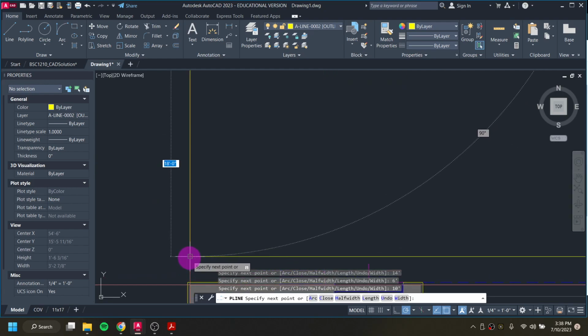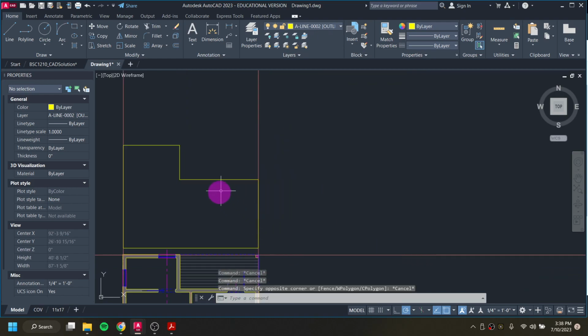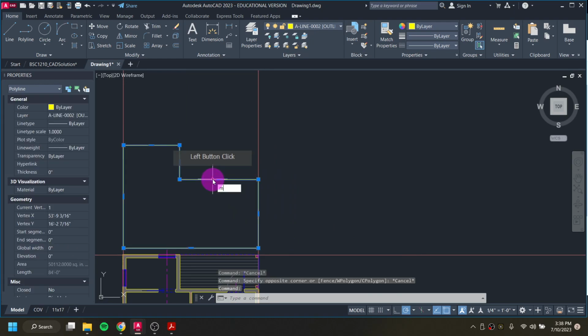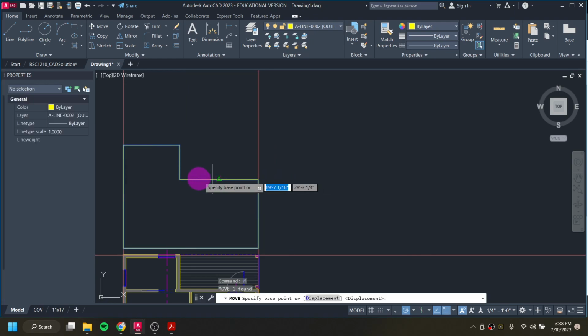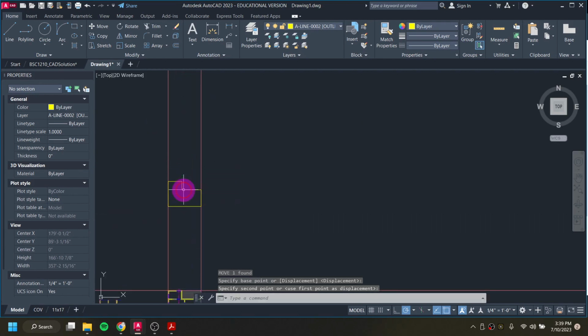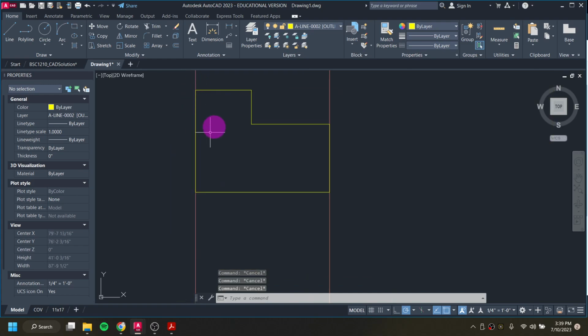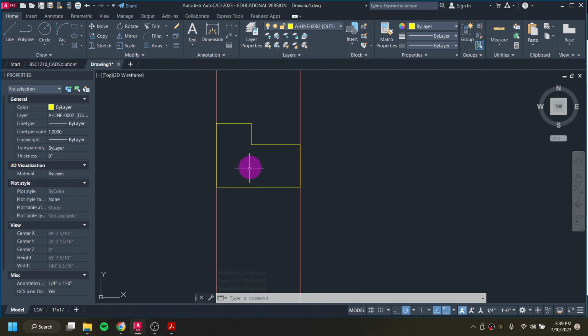And then I'm going to click to close it. And I'll hit escape to end the tool. I'm going to click on all of this and use the move command, M, enter, so I can move it far away because it was way too close. But this way, it's still sitting on my rays. I like it that way. That's just me being very particular about things.